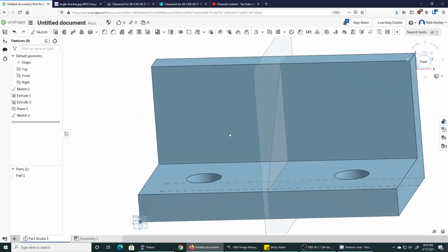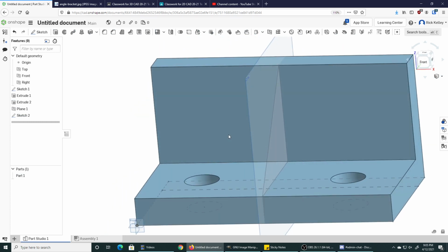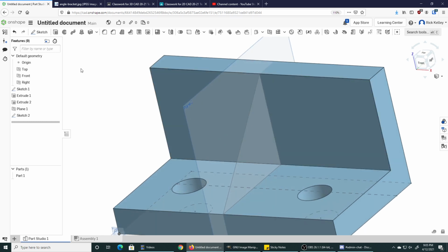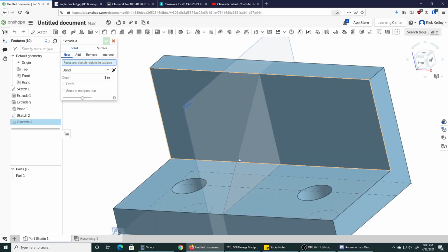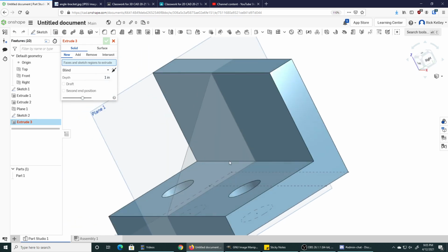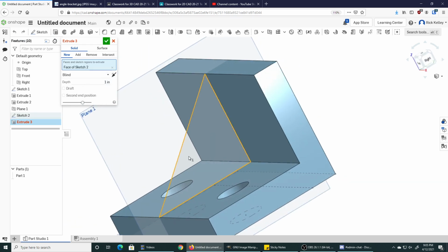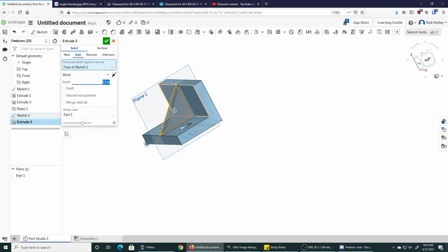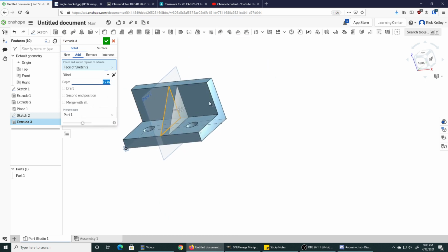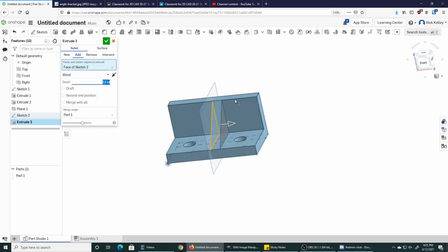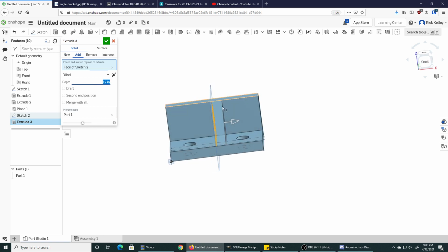Now I've got the shape I need directly in the middle of this object. We just need to extrude it. So if I click extrude, and whoa, didn't mean to orbit that much, and I click that shape, we could say 12. Now hang on, you're probably already saying, wait a minute, that's not right. Because that entire 12 went in one direction. I need it to split evenly. Remember, we made this plane right in the middle. We didn't make it 6 too far to one direction.